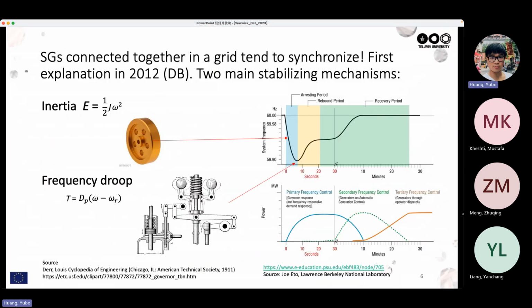I'm now talking not about what is written on the slide. So if you start in a power grid to replace the synchronous generator with inverters, and you don't do it in a careful way, which means you do not take care for the stabilizing effects to be present in the inverters, then the grid loses these nice properties, the inertia, the frequency droop, it loses them gradually. And as a result, it becomes unstable.